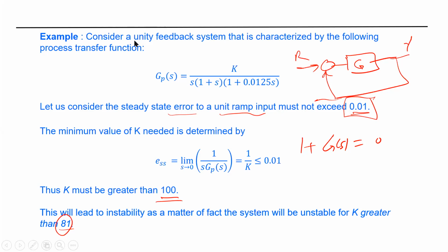Doctor, what exactly is relative stability? We know now that we can move the imaginary axis, let's say by 1 unit, and our system is still stable. If you move it further, maybe the system will be unstable. So how can we reflect this in our design? Can't we just use the Routh-Hurwitz criteria once and be done? What is the advantage?